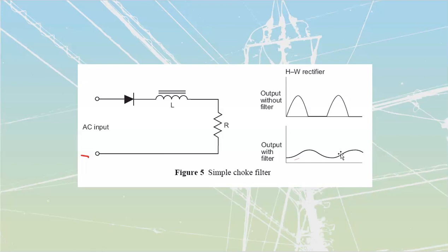They also have the additional benefit that these things are going to be fairly robust. Capacitors do have problems with overvoltages, harmonics, and things like that. Inductors are just coils of wire. You insulate them well enough, coil them tight enough together, they're pretty much bulletproof. They're an easy type of component to work with. So we'll use them on the DC side to filter stuff out.